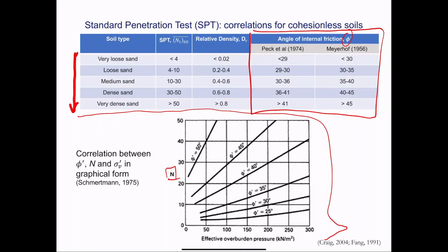Now, how does this fall in the context of our course? Well, if we're interested in relative density for compaction, then we can use SPT data to tell us whether the relative density has improved. For example, if you have a graph of depth here, and this is relative density, let's say this was before deep dynamic compaction, you're somewhere here, before, and then afterwards, you're here, then you can see the improvement and you can see whether your contractor did a good job. So this is how we make use of in situ testing.